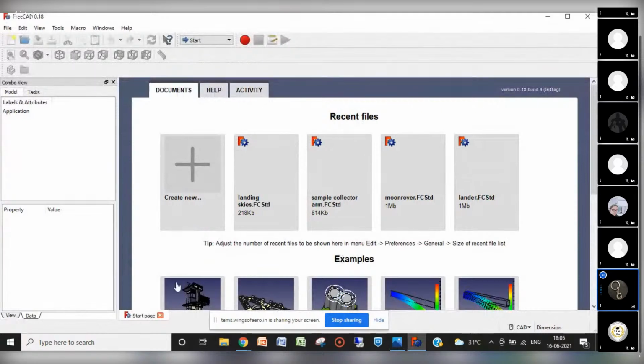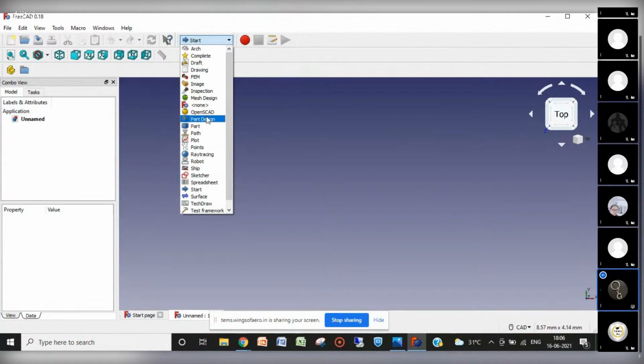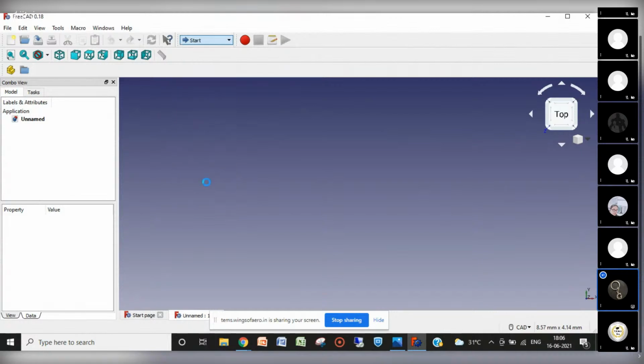Here, this is the welcome window for FreeCAD. I have also told this in the previous lectures. While creating a new project, click on New. This is the user interface where we start our designing work, our part work, and analysis, everything. From here, we need to choose Part Design because we are designing a single part, not an assembly. Let it open.